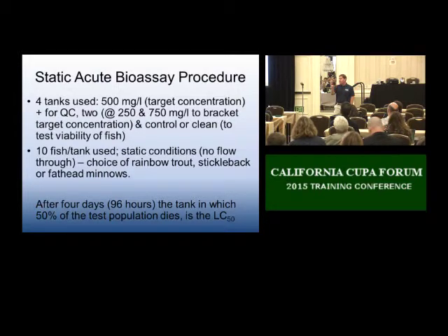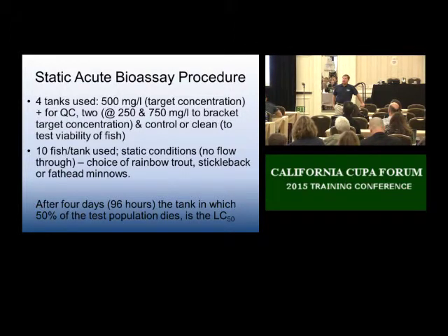Now, it may be that the pH is above 2 or below 12.5, but if I applied it regularly to mild steel, it would dissolve 6.35 millimeters, which is a 1/4 inch, of mild steel over the course of a year. So independent of pH, it attacks mild steel. Well, I only have 90 days to keep my waste. I've got to get rid of it. I don't have a year to figure it out.